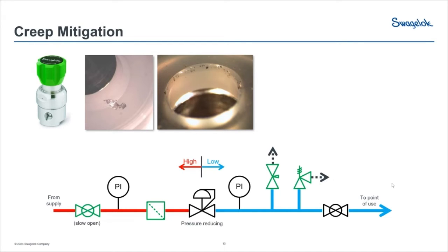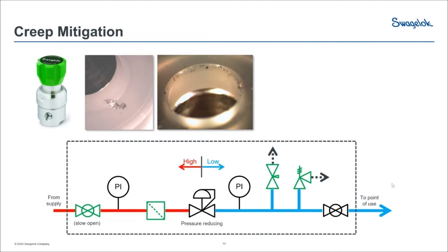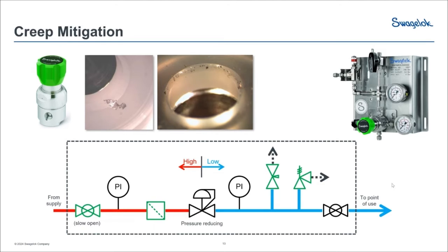So providing an upstream isolation valve to complement the downstream, and having provisions for appropriately bleeding off pressure so that regulator can be serviced is paramount. That upstream isolation valve is also really important, because another bad practice that we see is individuals using the regulator as isolation rather than using a true dedicated valve for that isolation. Now package those all into one common panel and you've maximized your convenience.